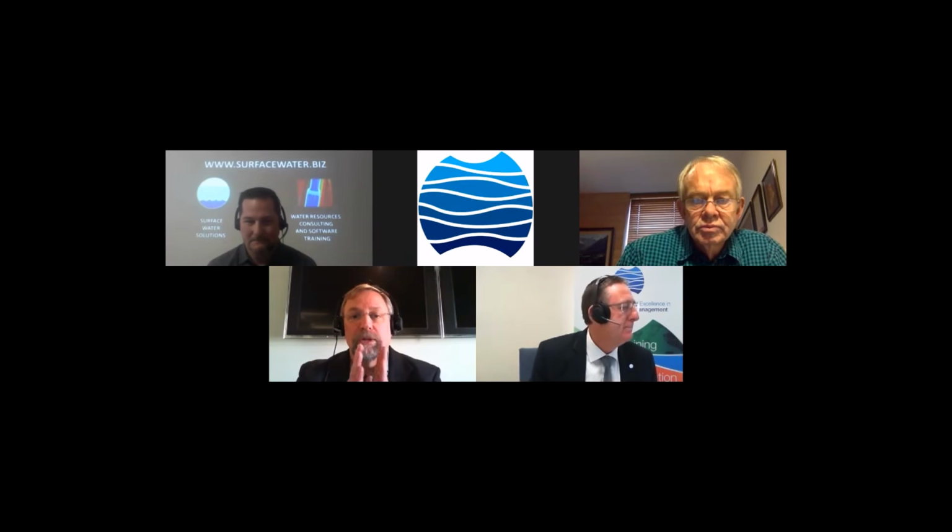Okay, Siash Joshi in New Zealand says, does the 1D section need to be extended in the 2D area while doing a 1D, 2D coupled model? No. Those two domains need to be juxtaposed, but never overlap. Otherwise, you're double counting the conveyance.